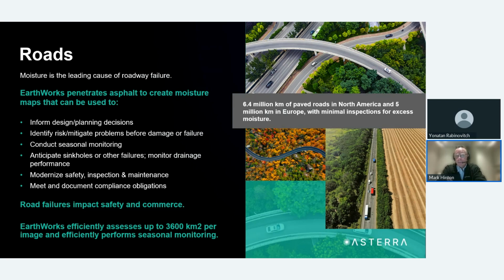You could avoid, perhaps in some cases, unnecessary manual inspections altogether. And for road and rail, for example, that can be a safety case. You don't want people out close to carriages if you can avoid it, or live traffic. And if mitigations need to be designed and constructed, maybe designing new drainage or retaining walls, all those types of things, they can be much better informed and optimized in the design if you have this additional level of site-wide insight.